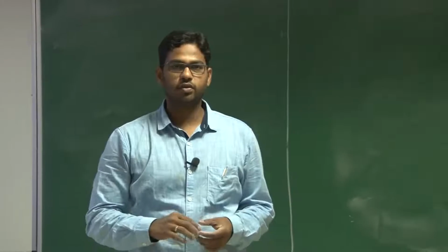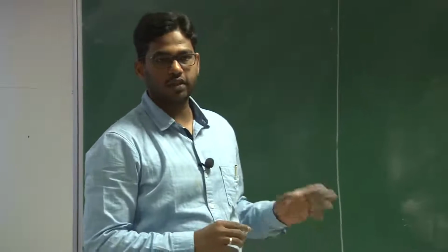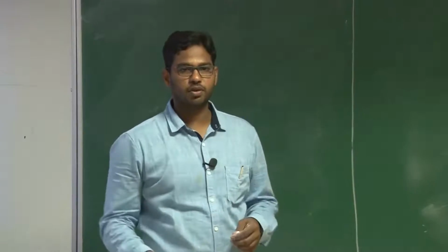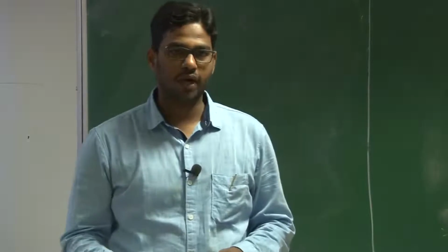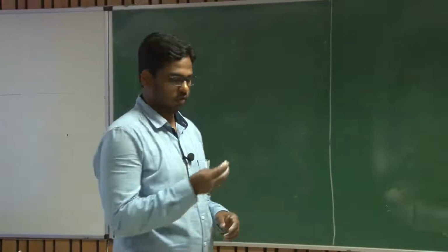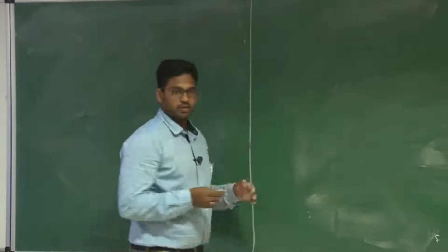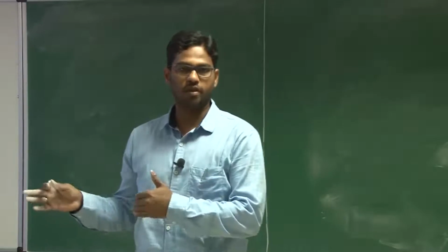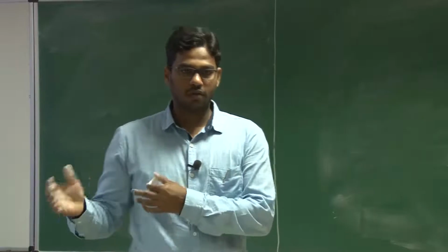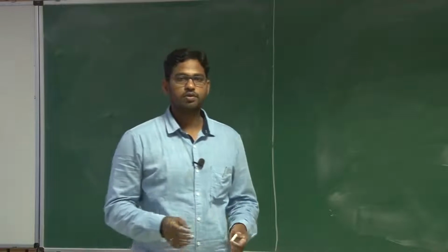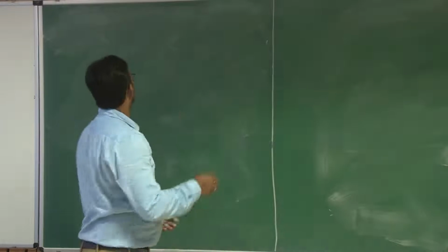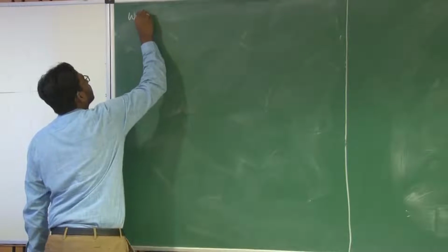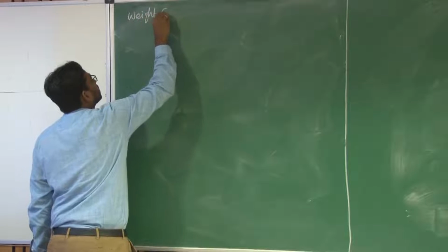So till now we assume that the weight of the aircraft or the UAV is given, but for a designer it is never an input. Weight is never an input. You have to estimate the weight of the system. So in order to estimate the weight, we need to understand how this total weight of the system is summed up. What are the components that are contributing towards this total weight? What are the major components? Now let us look at weight estimation.